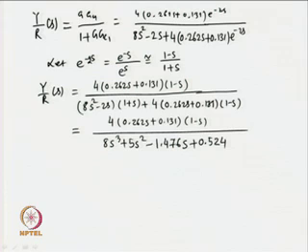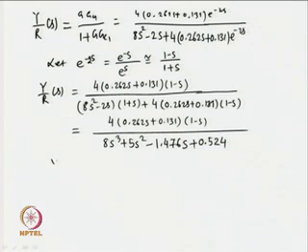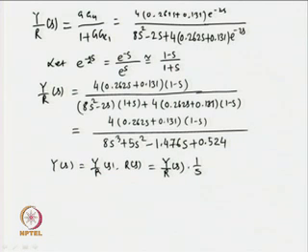Thus, to find the response of the closed loop system to unity reference input, we have to find the expression Y(s) equals Y upon R(s) times R(s), which is 1 upon s for unity step input. Then from there one can find its Laplace inverse and ultimately find the expression for y(t).